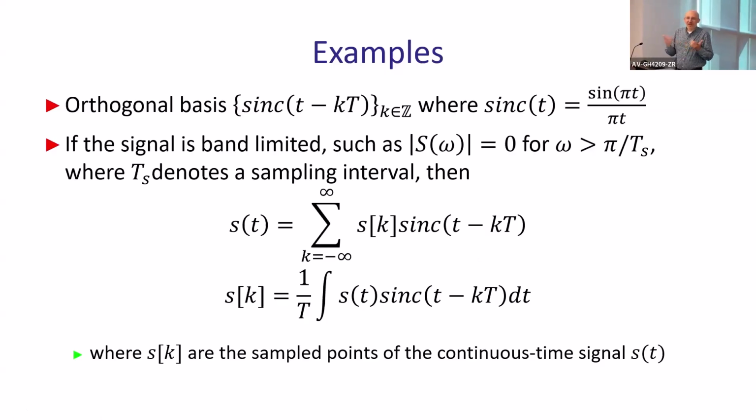Same thing: you represent that signal as a sum of coefficients times these basis functions, which is whatever we did before with the Fourier series. And magic, Sk is computed as the inner product between these two functions, exactly the same thing we did before. It is the inner product divided by T, because you also need to normalize it.